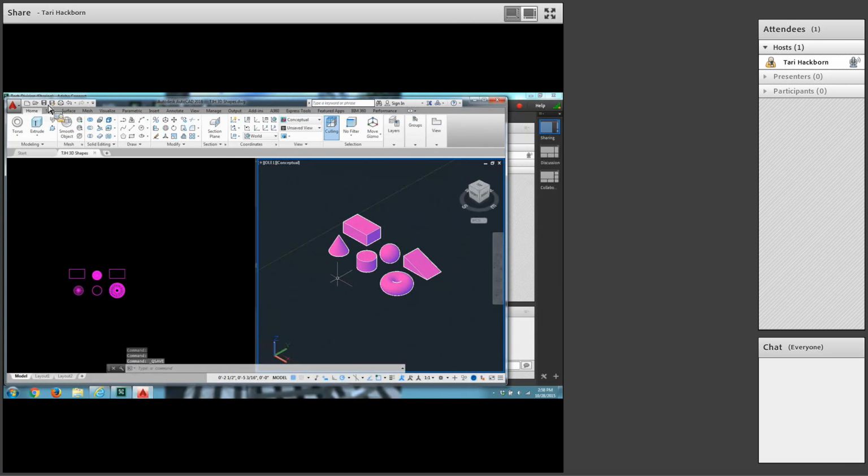Okay, now some extruded solids. At the bottom of page 52, it says to type C and enter. That just gets you into the circle command. And then type 1.25, 5 for the center point, and enter. Type 3/8 for the radius.